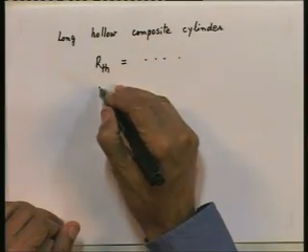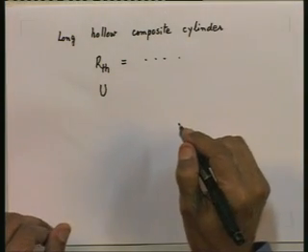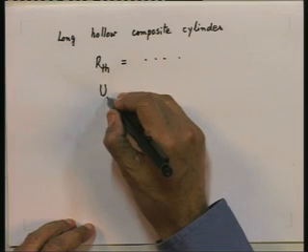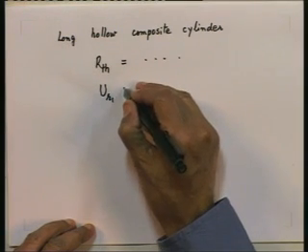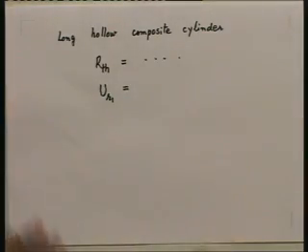We had derived an expression for the overall heat transfer coefficient for this cylinder, and an expression for the heat flow rate. So, we had an expression for RTH, the total thermal resistance. You will also recall that since the area through which the heat is flowing goes on increasing as you go radially outwards, we have to specify on what area we are basing the overall heat transfer coefficient. So, we derived expressions based on the radius R1, the inner radius of the tube, or we could have based U even on the outer radius R3.